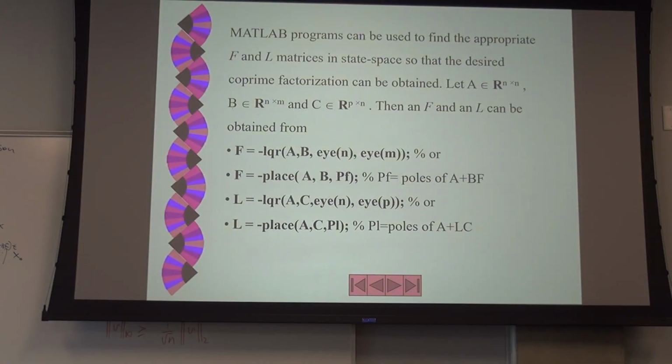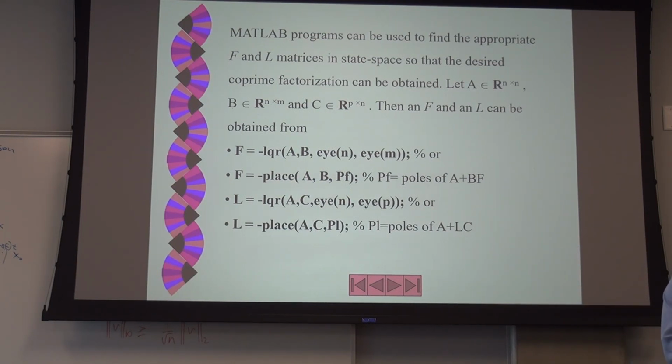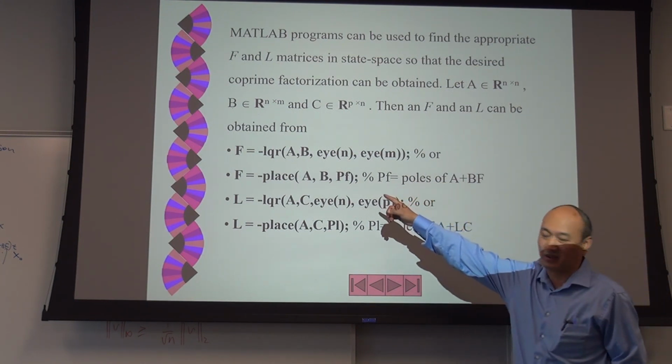What's behind is the formulation like that: the calculus of variation, the state equation, co-state equation, and algebraic Riccati equation, and the Lyapunov equation, and so on and so forth. So all these are condensed. You should pay attention to understand what's behind LQR.